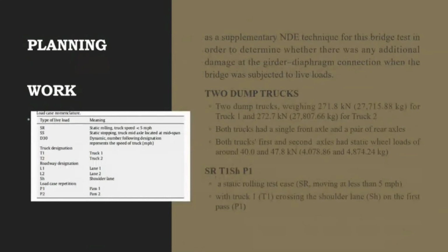For planning work, as a supplementary NDE technique for the base test, in order to determine whether there is any additional damage, we set up 2 dump trucks, which are 27.10 kilonewton for truck 1 and also for truck 2, and both trucks had a single front axle and a pair of rear axles.